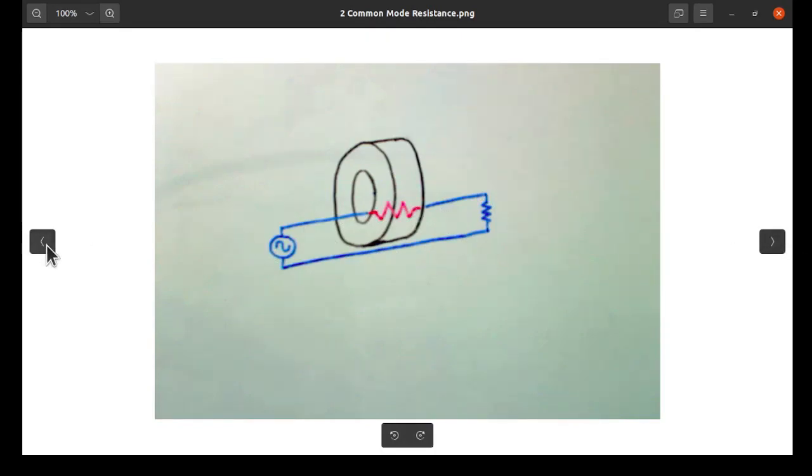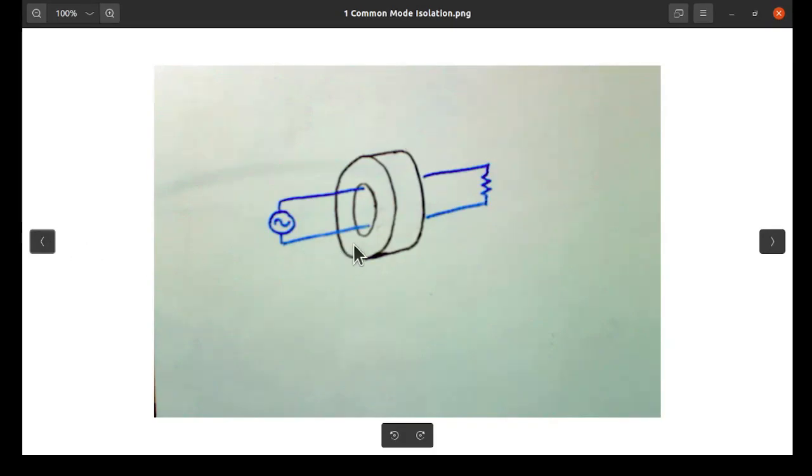Now, what's that have to do with this? Well, we don't have a common mode circuit here because we don't have a third plane of conductivity. Unfortunately, coaxial cables do, and as I mentioned before, this is a crude representation of a coaxial cable, and it's fine as it goes, but the shield of the coax actually has two surfaces.